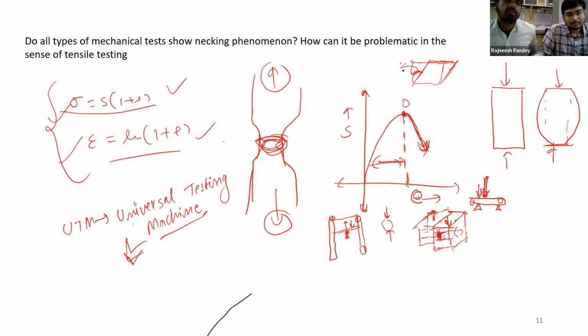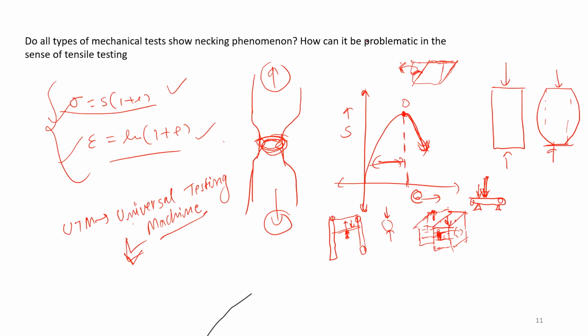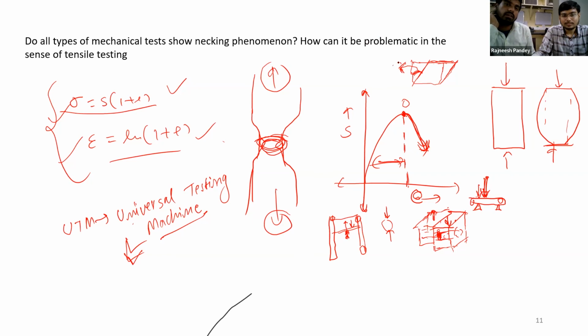No normal stresses are applied, only the pure shear case, meaning only shear stresses are applied. So from that equipment, you are going to get the shear strain versus shear stress, and some parameters from which you can calculate this. Okay, Sanjit? Yes, sir. So for that you have a separate machine, but for the compression test, the tension test, and even the bending test, you are going to use the UTM itself. That's why it is called universal, because it is used for multiple purposes.